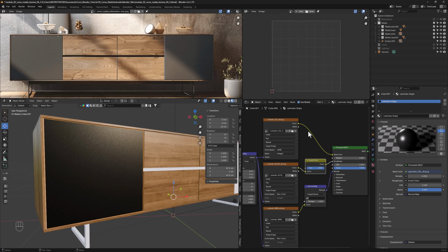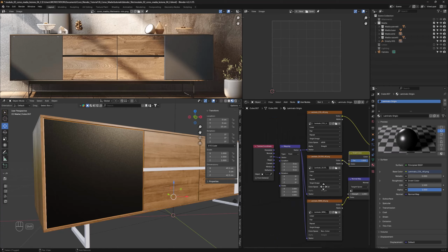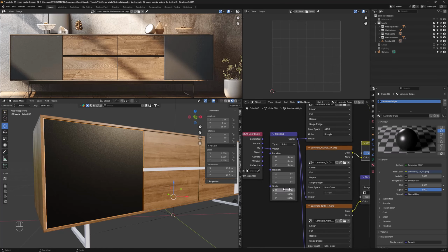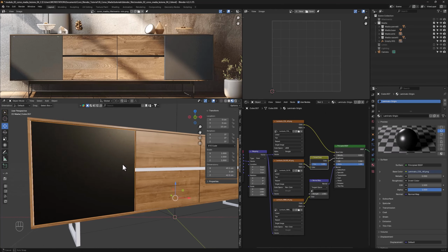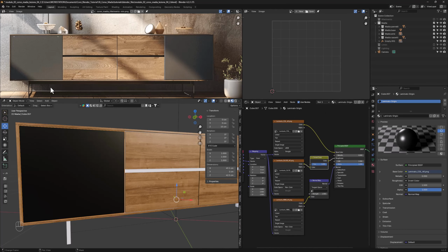Looking closely at the material, we notice that the texture appears excessively grainy. To reduce this effect, simply change the X and Y scale values, setting them, for example, to 2. Comparing the material we've obtained with the original from the reference image, we notice that ours is darker.